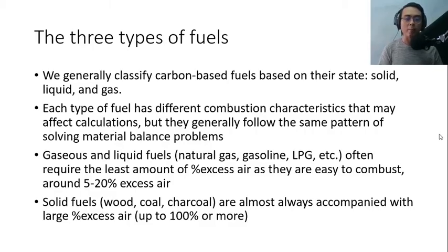So what would happen if you did not supply the needed percent excess air? There are several things that could happen. One, and the most likely, is that you could be promoting incomplete combustion. Again, a telltale sign of incomplete combustion is that your product stream contains less oxidized species such as carbon monoxide and even elemental carbon. So if you're seeing that in your products, one of the main remedies is to simply increase the percent excess air.